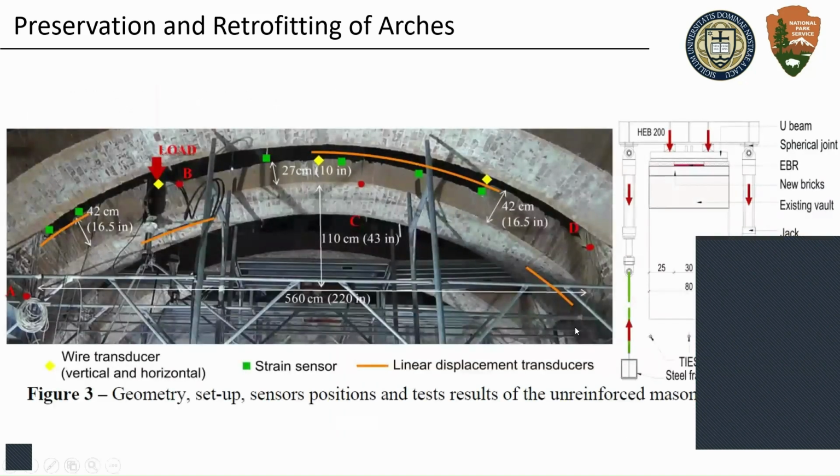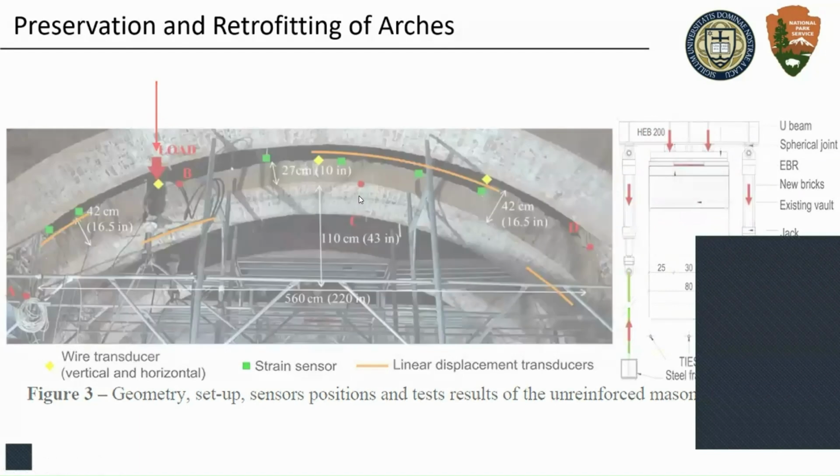This is how they tested this. So basically, you see the vaults here, 1, 2, the arches, I should say now. We are loading these downwards, similarly to the example that I showed you with limit analysis, and this is how they do it. They have some hydraulic jacks and a beam, and they push downwards until you fail the arch. And then we can monitor basically 2 things. We're going to monitor how much force we apply and how much displacement we are measuring.